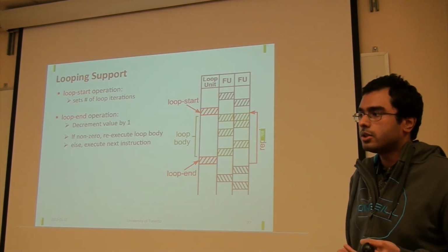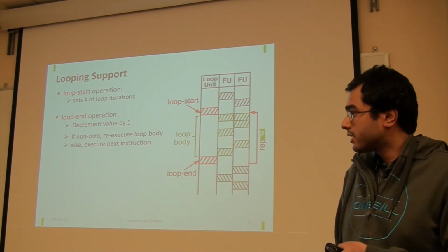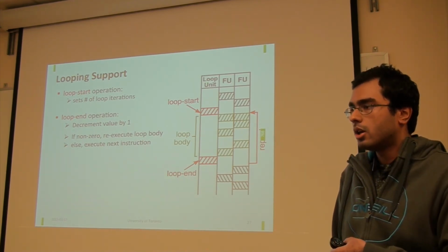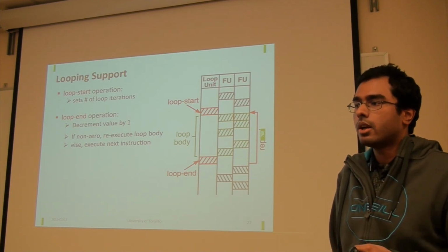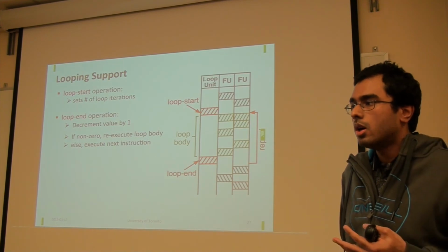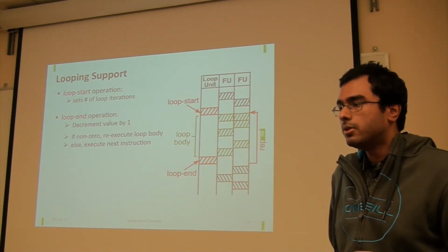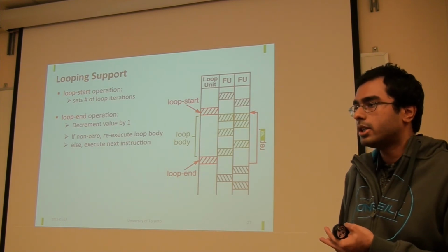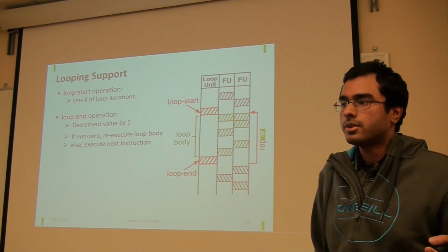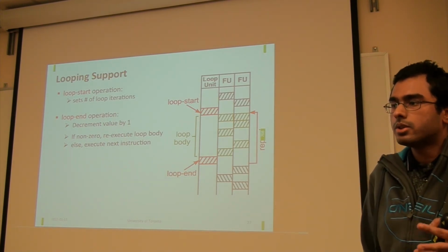In a similar fashion, when we schedule the tilt schedule onto the target architecture, as the schedule is running, we track how many bank conflicts there are, or how much the FUs are not being reused. If you could schedule an FU operation on a certain cycle, but because a resource is unavailable we cannot schedule it, we use that as a heuristic.